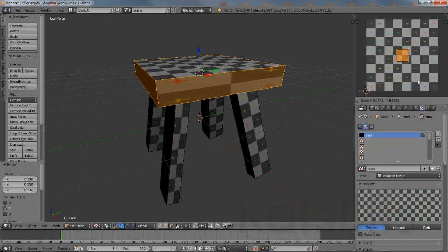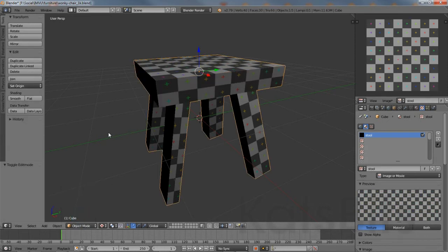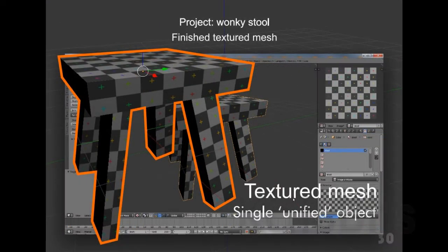When changing the horizontal seat UVs, after initiating resize, press the X key, locking movement to the horizontal axes. Manipulate the mouse, left-click to confirm. Once all the UVs have been adjusted, left-click the Mode selector, then Object mode to exit Edit mode. With the image UV assigned, it and the Blender project can be saved.